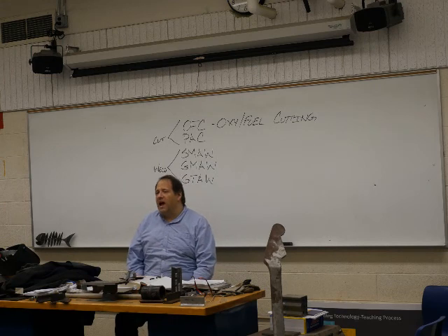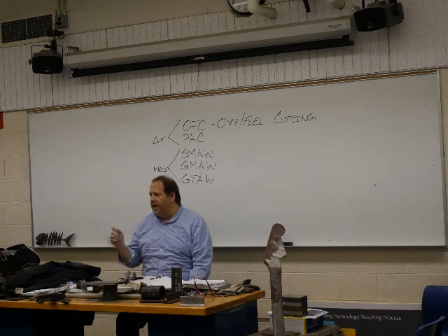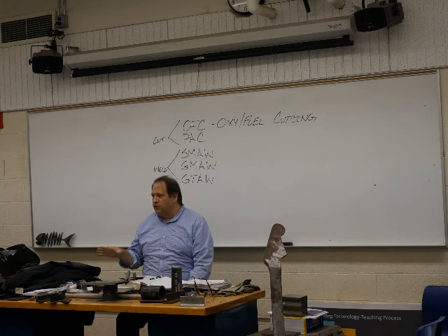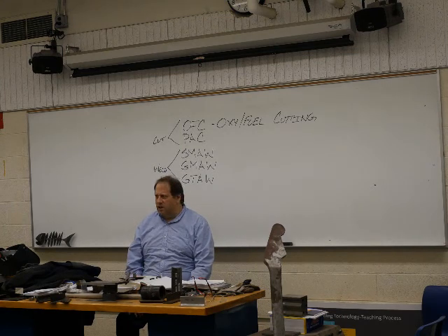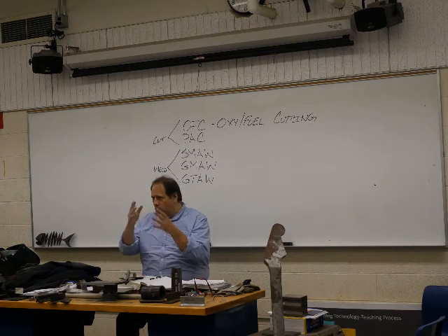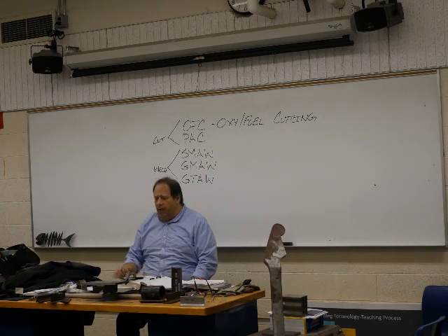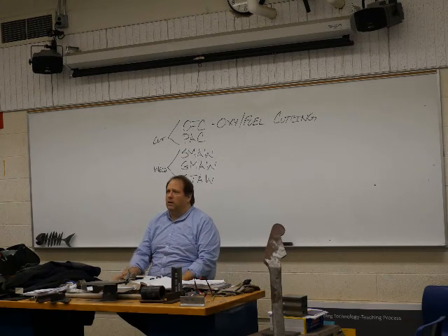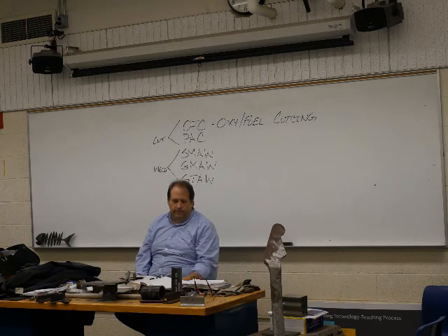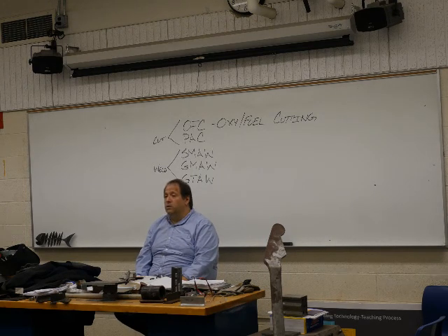So what we're doing is we're actually oxidizing, we're not cutting through heat. What the torch is really there for is to heat the piece up. And we're getting it just underneath the melting temperature. If we melted it, it would just melt. It wouldn't actually have a cut line. Okay? So what is the melting temperature of steel? Take a guess. Throw something out there. 2,500. Close. Very close. 26 to 28, depending on the carbon content.